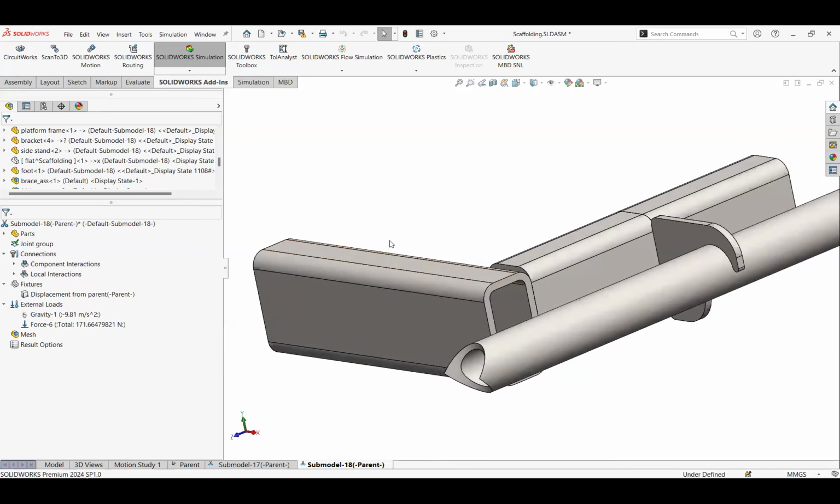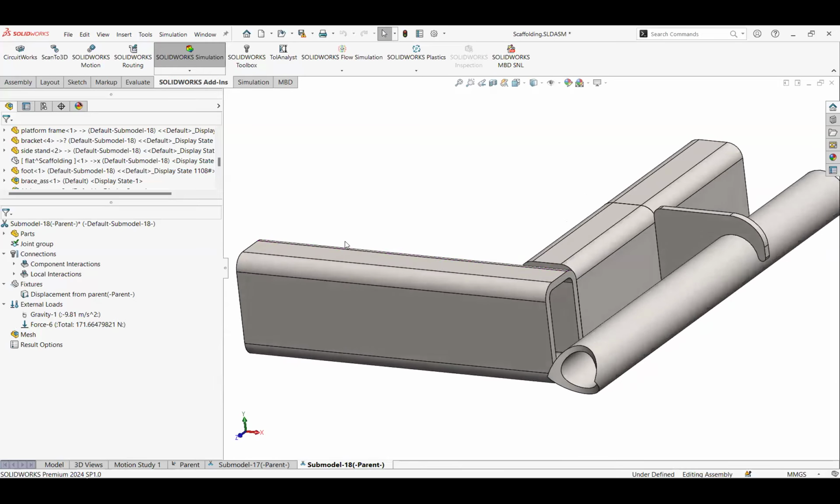But now we've zoomed into this model here. And in my study setup, I still have gravitational pull, and it's based off of the center of gravity of the whole model. But the convenient part here is that it takes the forces, all those live loads, that dead load, and it proportionally distributes that across whatever's left in my study. So it does that calculation for me. And then at that point, I can run the analysis. I can then maybe apply additional meshes on the model here. And I've already run this so you can take a look at it just to save some time.